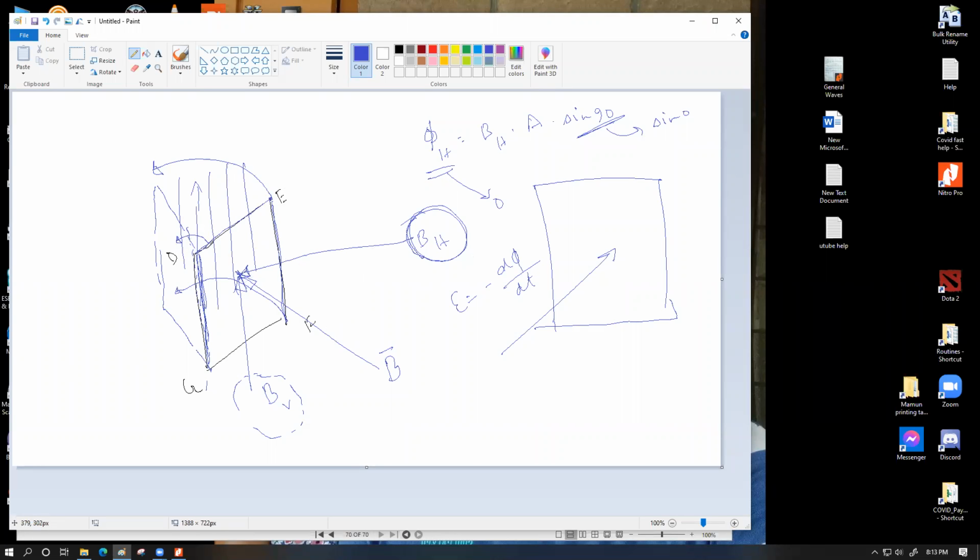If you connect a voltmeter just across the D and E part, you're going to get an EMF because of the cutting of this part. If you connect a voltmeter across, let's say, halfway of DG to halfway of EF, you're still going to get that EMF value. So technically speaking, the measurable EMF would be available across the DG and EF part.